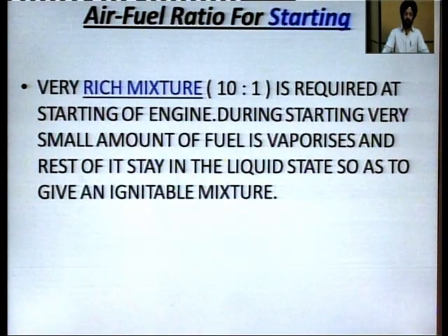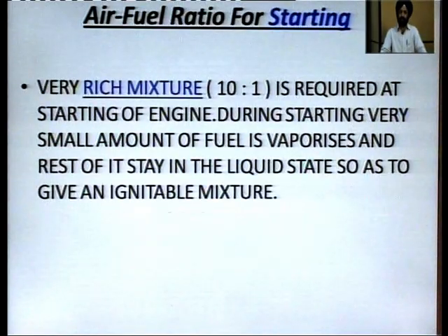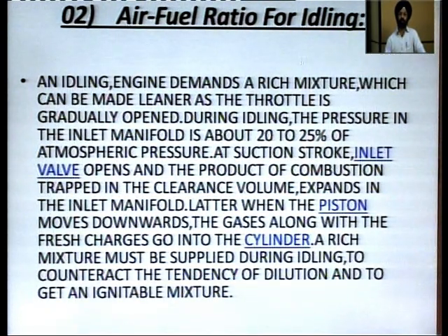Now, what types of mixtures are required for different running conditions of the engine? First, we have to start an engine. So, the air fuel ratio for starting: a very rich mixture is required. The engine is cold and we want to start it. A very rich mixture is required during starting because during starting only a very small amount of fuel is vaporized and the rest of it stays in the liquid state, so as to give an ignitable mixture. So, initially when the engine is cold and we are starting it, a rich fuel air mixture is required. Then the air fuel ratio for idling.